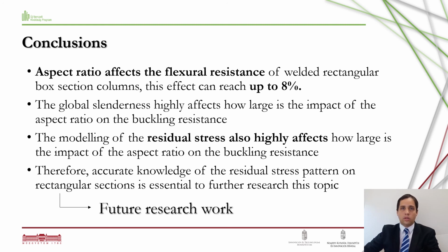It is shown that this resistance decreasing effect of the rectangularity strongly depends on global slenderness and also depends on the applied residual stress model. And therefore, to further analyze this topic, accurate knowledge of the residual stress pattern on rectangular sections is essential. However, there are only a few residual stress pattern research for rectangular sections in the literature. Therefore, this needs further experimental research to have an appropriate knowledge of the residual stress pattern on rectangular sections.